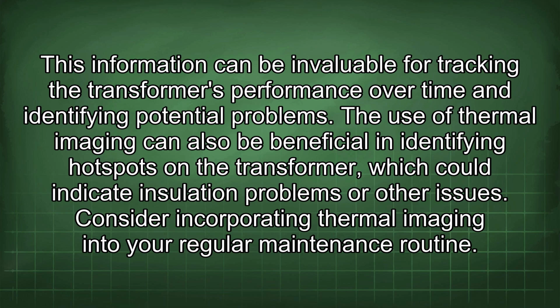The use of thermal imaging can also be beneficial in identifying hotspots in the transformer, which could indicate insulation problems or other issues.